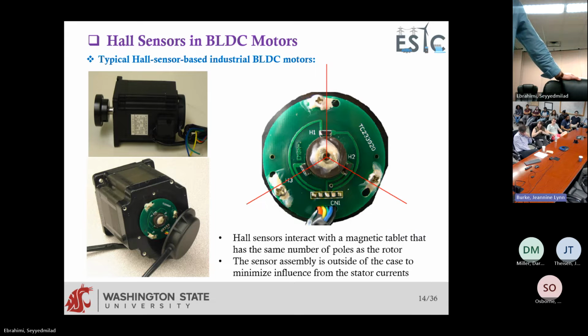I think that is one of the things that we can improve on, because potentially yes, that can be improved. Because the thing is, what I've shown here was just the conventional methods, 120 degree and 180 degree. And if you buy a BLDC motor, I would say 90% of the time you'll see that they have 120 degree control logic embedded into their system. But obviously, yes, there are always ways to improve it.